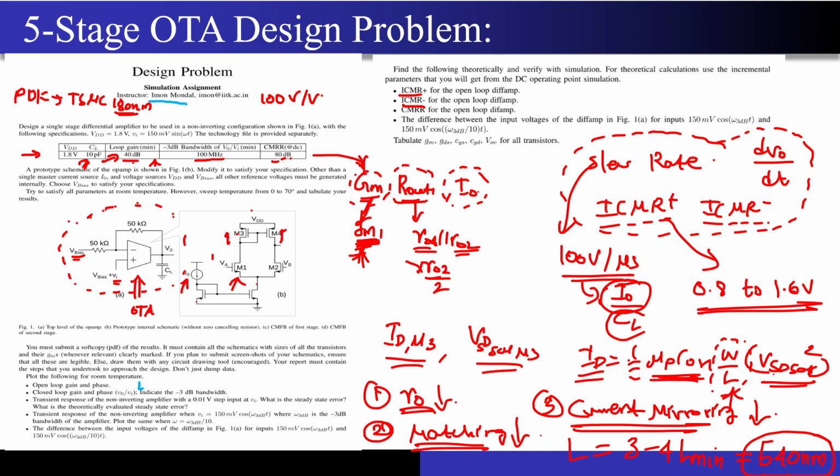Correct? Now, once this is done, what about this particular transistor? So remember, whatever current this particular circuit is consuming, if you consume the same current in your diode connected load, then the power consumption of the entire circuit becomes 2x. Correct? The power consumption becomes 2x, and that is not a good practice. So the current that is coming over here, for this example, we will assume that the same current is flowing like this, but when you practically design the circuits, the current that you are dumping into this transistor should be at least 5x or 6x smaller than the current that this entire block is consuming.